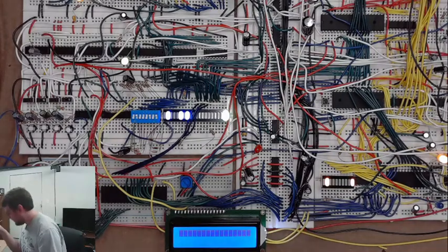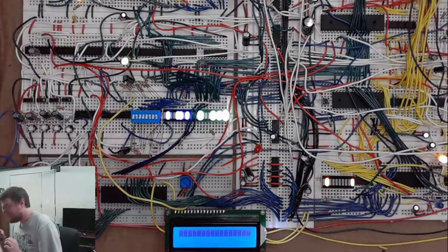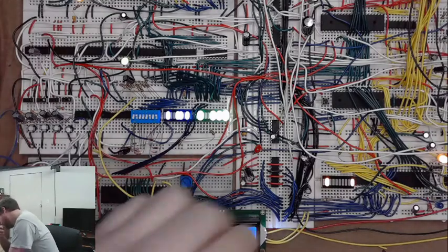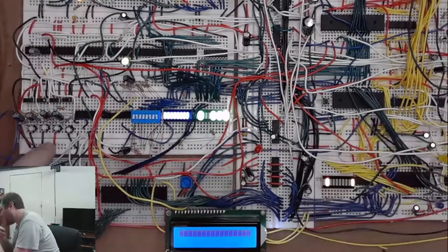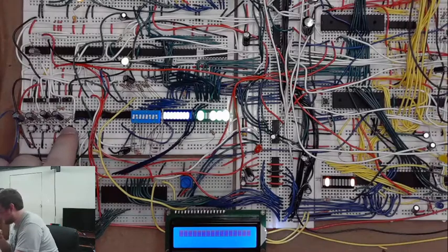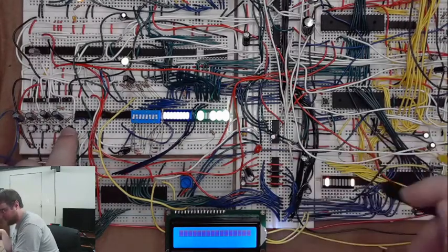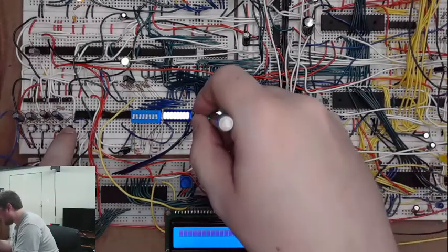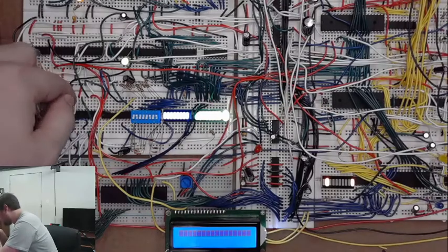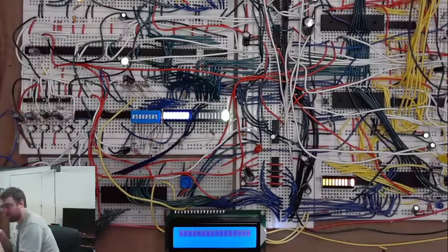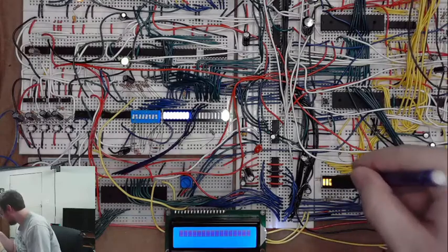Let's get to programming. I can still increment the counter, but you have to have load not enabled. Alright, so the easiest way to switch this back to 0 is to disable everything. Press this, you'll get it back to the highest one, and then just roll it over to 0. And that's the easiest way to do it.